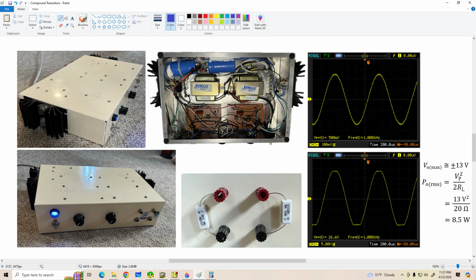So when you're doing testing, if you don't want to use a loudspeaker, which is probably a good idea, connect a power resistor that's about the same resistance as your loudspeaker across the terminals. I used 10 ohms, but 8 ohms or 12 ohms would probably work just as well. We'd get different power output levels, but you just have to use some kind of load on your amplifier.